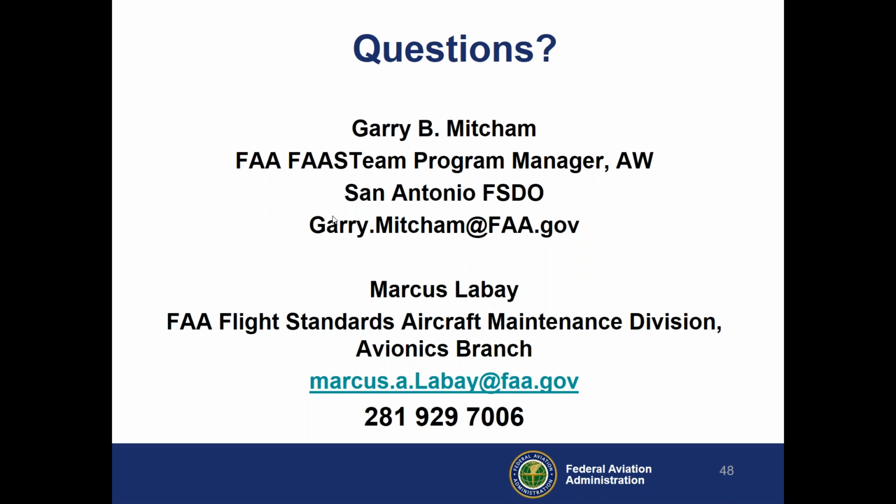So really the core issue has to do with the broadcast of the barometric altimeter data that gets processed through the ground system and makes it onto ATC. And therefore we have the hazardous and misleading information that other aircraft and flight crews or other pilots or controllers may see that can, quite frankly, cause a panic. And Mode S transponders that coordinate with each other can issue traffic advisories, resolution advisories, et cetera. And therein lies the core issue that we've been trying to get this message out.